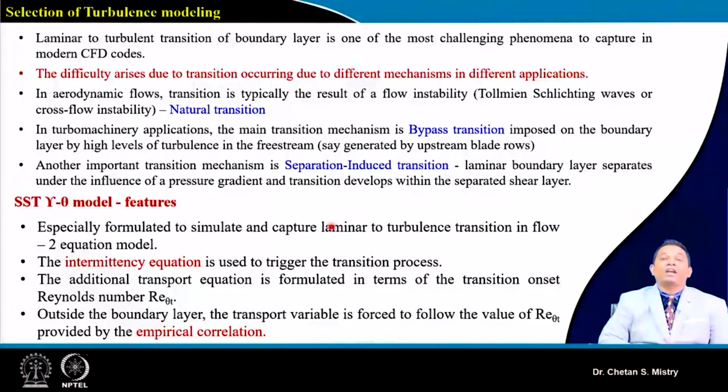So now we are having different turbulence models. Now let me tell you one more parameter, which is called turbulence intensity. When we are doing our analysis, suppose for a cascade tunnel, it may be having a low turbulence effect. This turbulence effect will be bringing the change of this transition on the surface. So mainly in the initial stage of analysis, this turbulence intensity we are assuming as 5%.